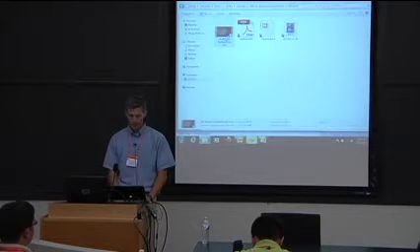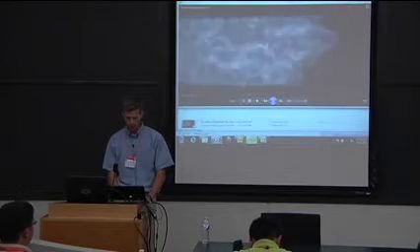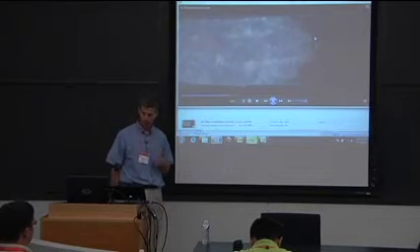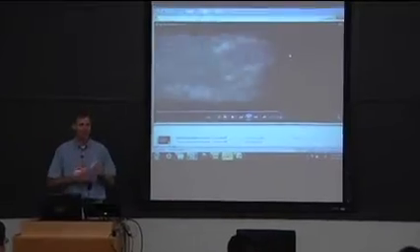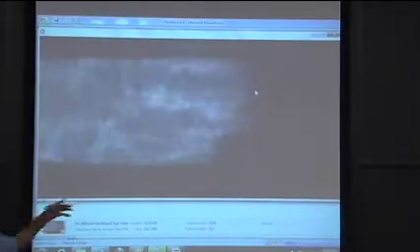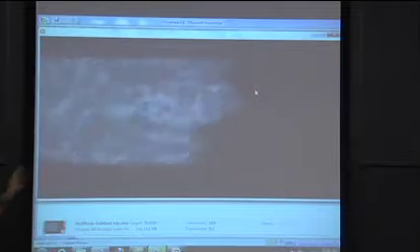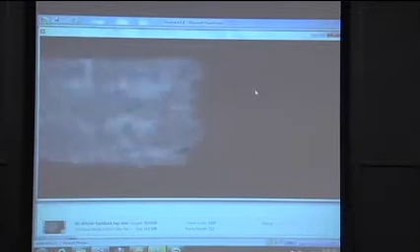So this is some really neat data taken from Thomas Sattelmayer's group in Munich of a flashback. And what they did was they created a, quote, a steady-state flashback. They created a diffuser with just a very slight incline. And so that flame is statistically sitting at one spot. And look at that flame swimming upstream, but you see it washes down, and you see these fingers shooting upstream.